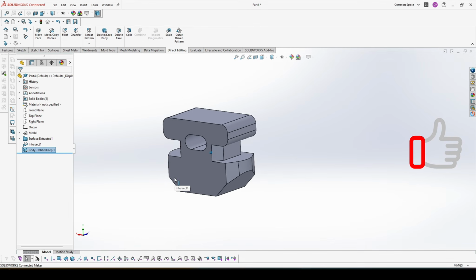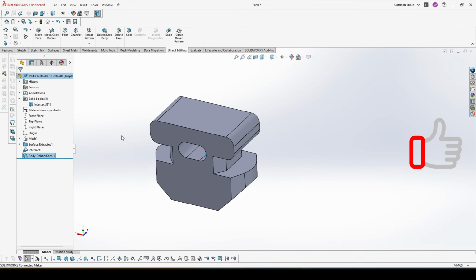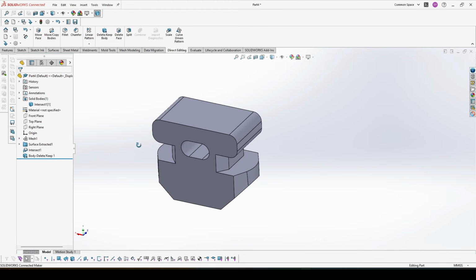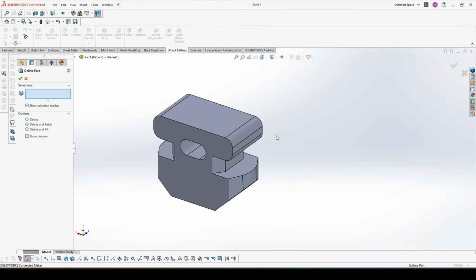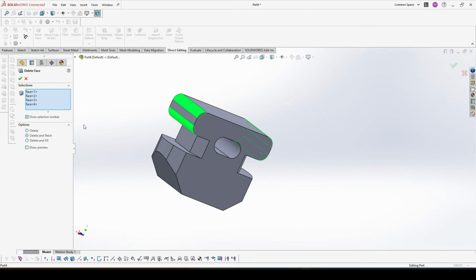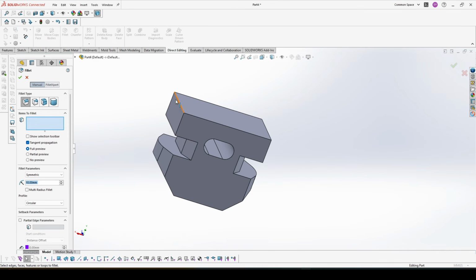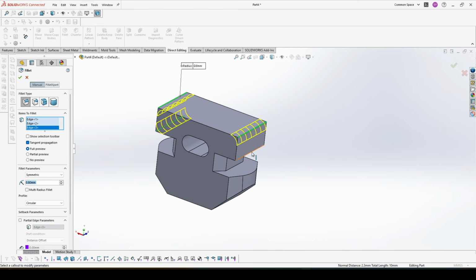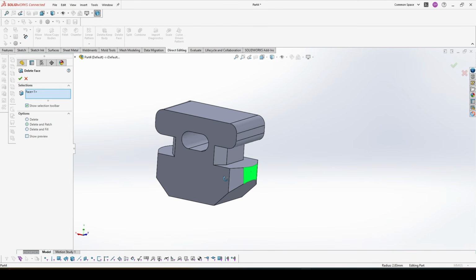And this is our SolidWorks feature. As you can see here, it's a feature body, not a mesh body, which we can modify or do whatever we want. For example, I can delete this face or all these faces. And make a fillet, so I'm sure that here is a correct radius and not some strange curve. And the same I can do for this here.